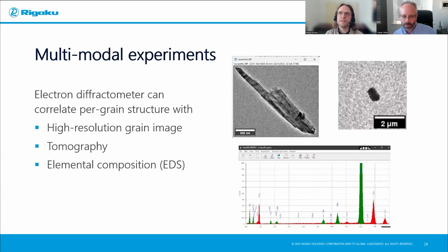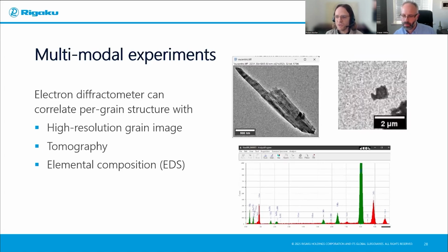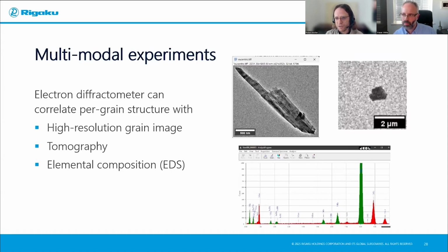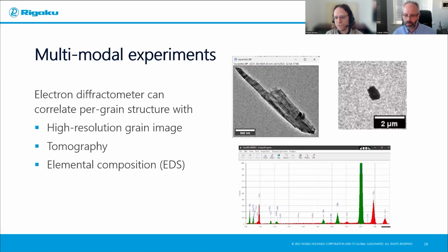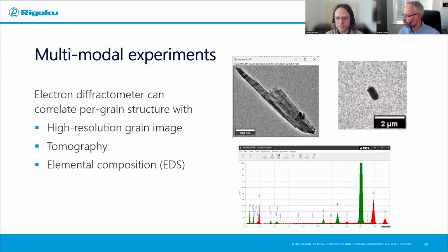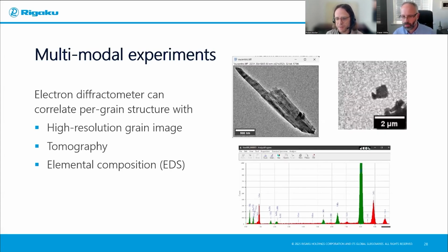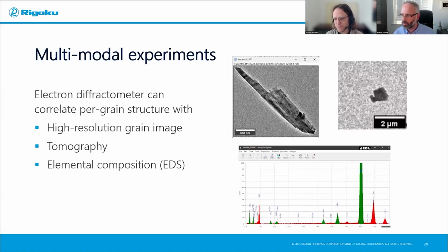Let's say if you had an infinitely great goniometer and a very, very small beam, then you could at least minimize those effects, I would say. Practically, for almost all applications that we're looking at, it's not a limitation to find grains that are spaced from each other by, let's say, at least 1 or 2 microns, which matches quite nicely with the typical sphere of confusion you can achieve with a realistic goniometer.